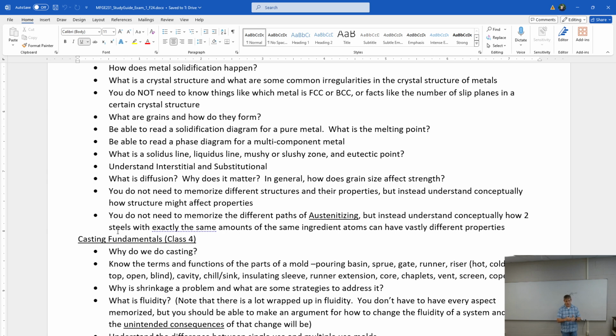If you have dislocations intersecting each other or intersecting any of those other things, then you can't continue to strain the part without adding a lot more stress. So that is strengthening or strain hardening of the material. It's increased the strength of the material, reduced the ductility of the material, and that's either good or bad depending on what you're planning to do with it. And we should be able to explain why.